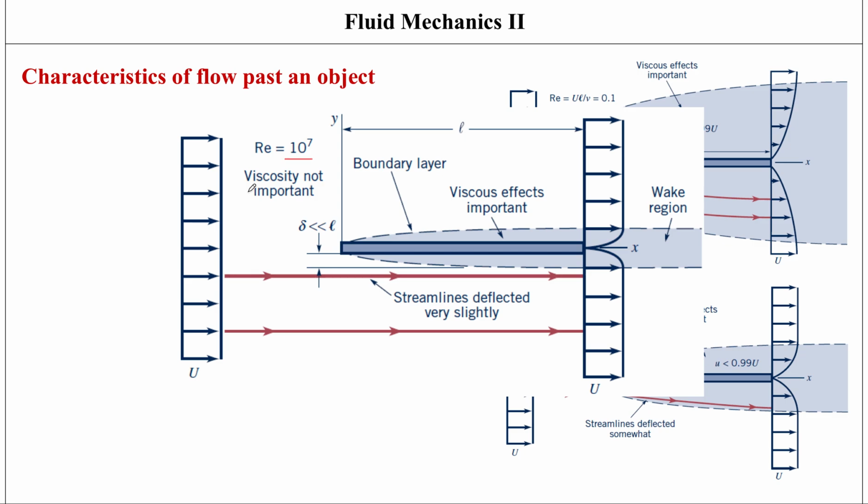but obviously that does not mean that the actual viscosity of the fluid is changing or something. The viscosity is the same whether it's within the boundary layer or outside the boundary layer. It's just that the relative importance of the viscous effects, and that is because the velocity gradients that I just previously explained, is different within and outside of the boundary layer.